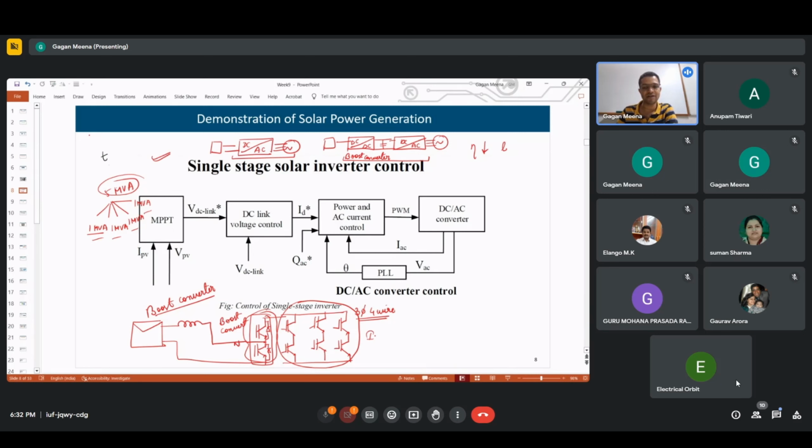So here also, to do this passive balancing on DC, balancing during both charging and discharging has to be done. For charging, one DC power supply is considered, and for discharging, a rheostat is considered. So it will act as a load. It will discharge the battery. This balancer IC will try to maintain the same voltage across all the cells.